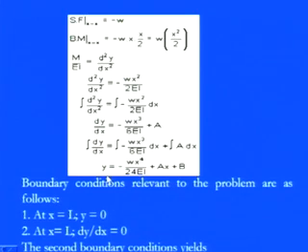From this UDL, the loading is coming in the downward direction, and at the support, which is exactly at the extreme right corner, the support reaction is coming in the upward direction. So with this, the shear force is negative, and it is in the hogging portion. So again the bending moment is also negative as per the sign convention of shear force and bending moment.